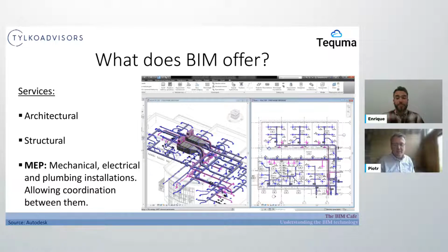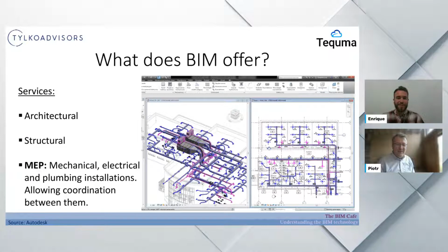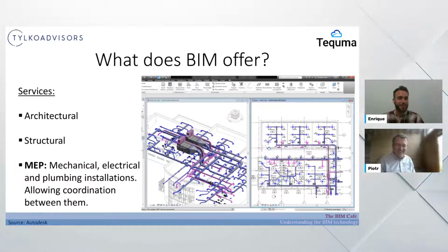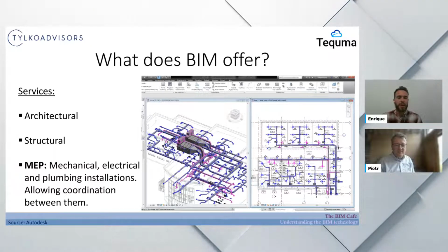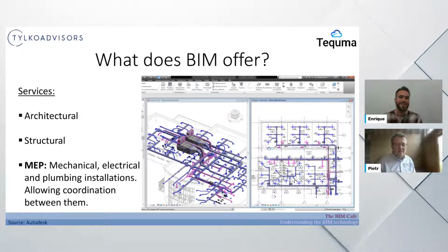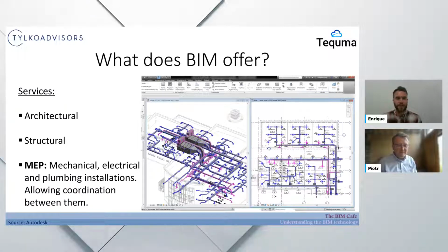Yeah, completely. And this is for the Wi-Fi points, for example, the IP points is a very interesting thing, as you need to plug them. No? We need electricity. The Wi-Fi points need electricity, so it's important for you to have the electricity network or see where the plugs are, because an internet cable cannot run more than 90 meters by law. Otherwise, the performance can be worse or something like that. Or I want a Wi-Fi here, but I don't have the plug there, so I cannot put the Wi-Fi there. So it's important to have this coordination of services and have them all in the same place, so you can check other people's networks as they might affect your work as well.